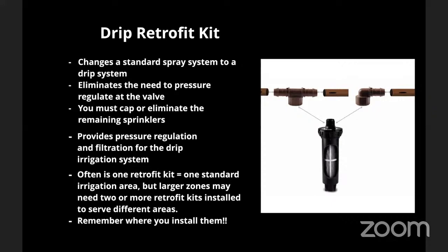If, however, it's greater, you can generally leave 2 sprinklers on the irrigation system, and it's best to have those sprinklers spaced kind of across from each other in terms of the layout, and then convert both of them. And normally that will be just fine. One can cover 1/2 of the area, one can cover the other 1/2 of the area, and that's coming from a 3/4-inch valve. If you're a large property and you have more valves, you might need to do more than 2. However, at a certain point, it becomes worth it just to put that pressure regulator and filter at the valve.